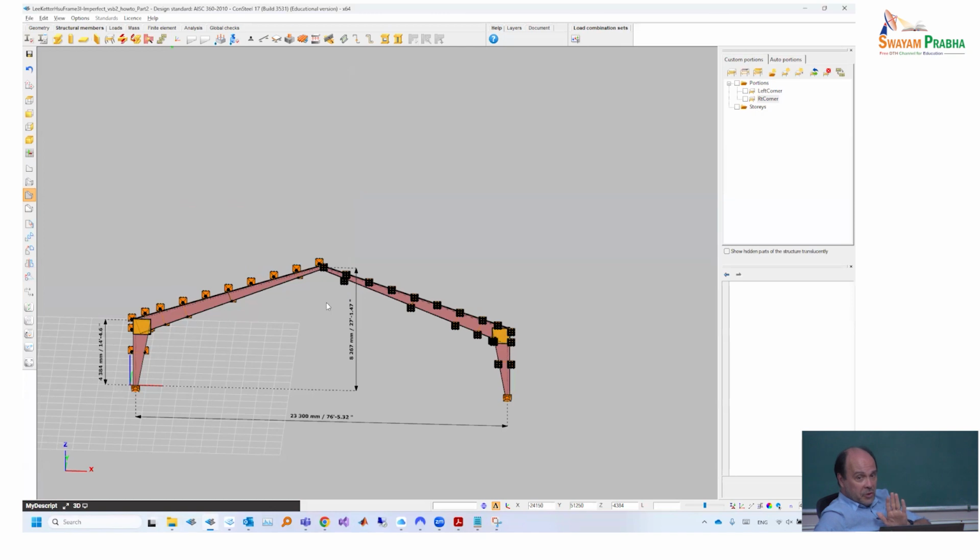Don't forget, we don't have out-of-plane loads. So all the internal forces are in plane, no warping, nothing. But there is warping in the buckling modes, which we will use to calculate the slenderness. So even that must be correct, not only the internal forces we are designing for. These buckling shapes are exactly as important as the bending moment diagrams.